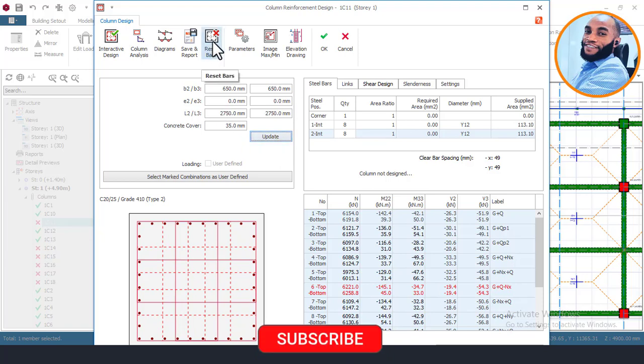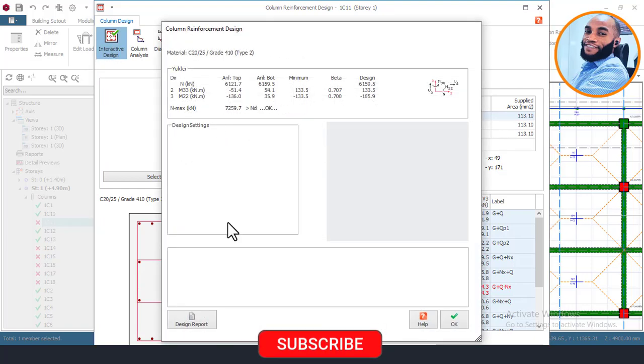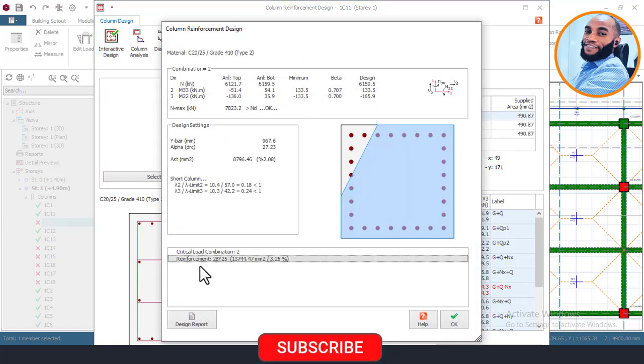Always reset bars, okay? Right now, as that here is showing 12, which is not okay, I'll come here and reset bars, and then click on interactive design here and wait again for the design. I can see that it is giving me critical, the same thing again, and showing 25 and 20. So once you're able to see the size of your reinforcement for your column, that column is perfectly okay.